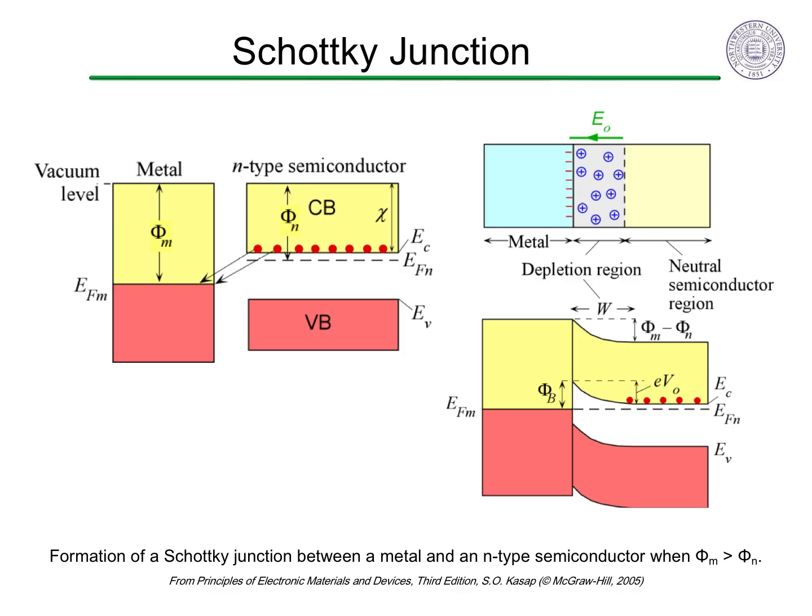As we saw in the p-n junction, the n-type material here will be depleted of electrons and become positively charged in the space charge layer. The metal will gain electrons located at the interface, which we can think of as an extremely thin space charge layer. Recall that the thickness of the space charge layer depends on the doping level, with thinner space charge layers for higher doping. So the metal with an extremely high charge carrier concentration acts like it has an infinitesimally thin space charge layer.